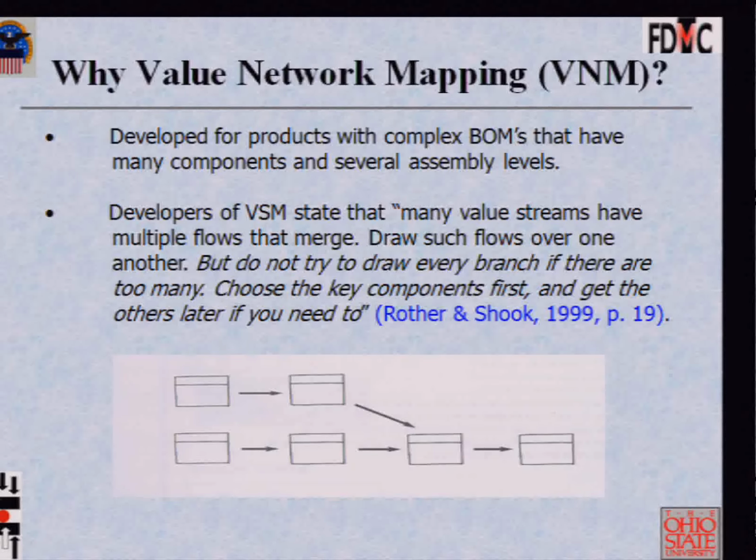If you look at products like tanks or scales, of course they have components whose routings are identical, or they'll have a typical goes-into structure. Components will become sub-assemblies, will become the final product. So yes, you will have flows that merge. This is the main product, and that builds up into multiple sub-assemblies, and that's how it goes into. This is a structure called the goes into chart.